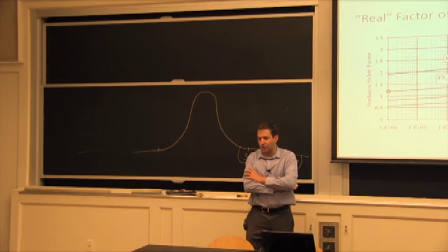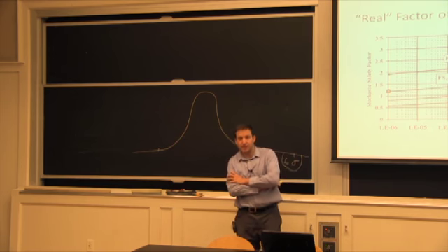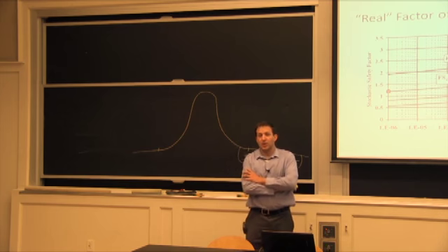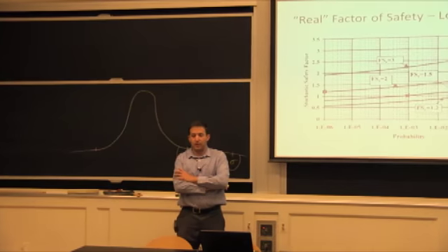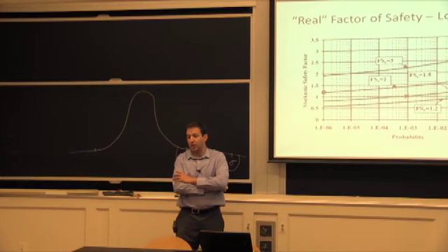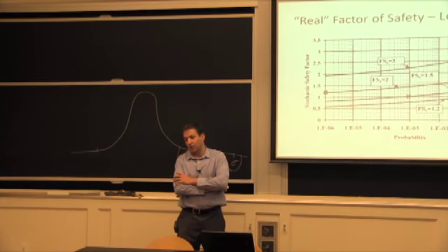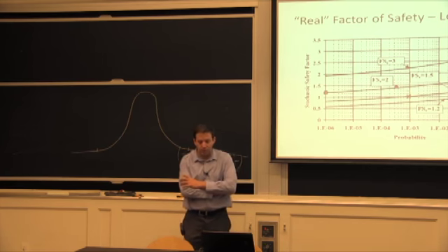I remember going through some numbers to realize that 80 or 85% of the load was the dead load on the bridge. And everything with the cars and everything you can think of is just 10 to 15%. So it wasn't a whole lot of fatigue. There was some fatigue, but from my perspective as an engineer, it was more loads that were not necessarily taken into account, or things that were not taken into account in the design in the first place. And it's very hard to go back.